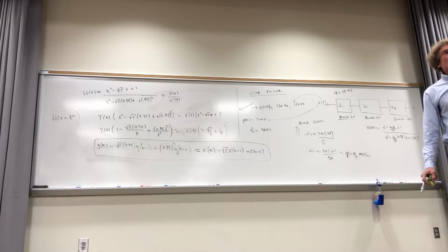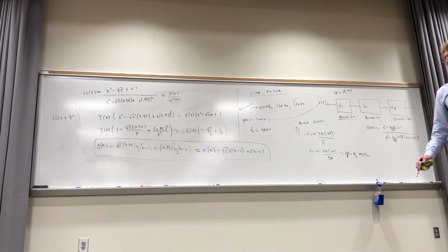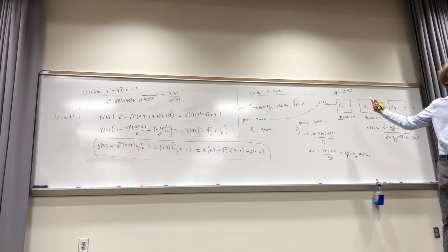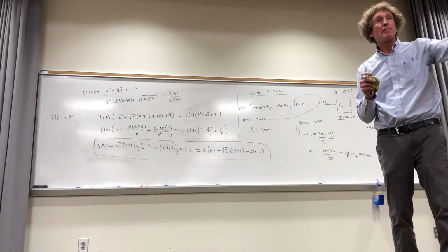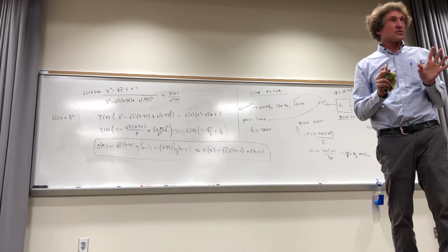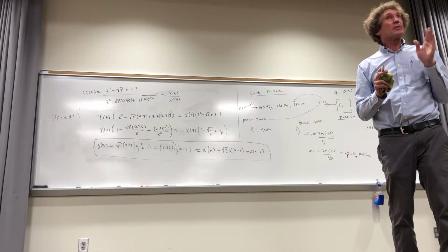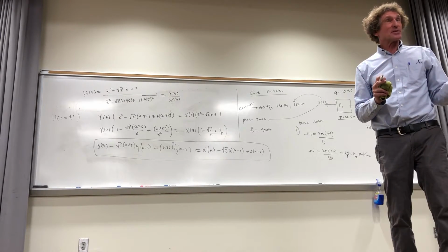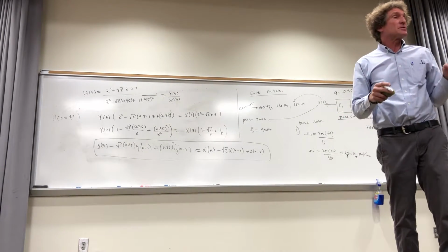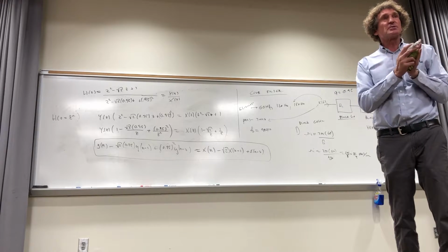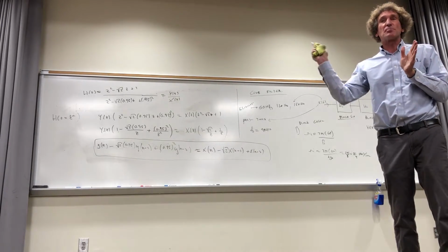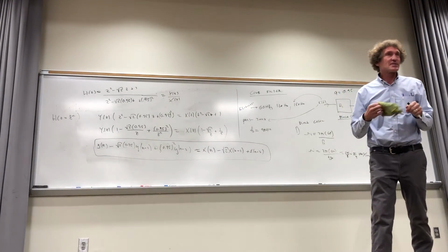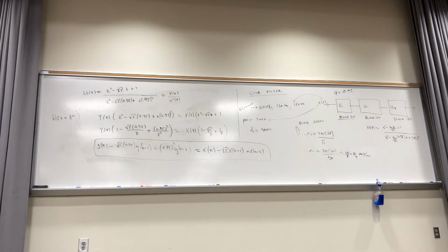Now, that doesn't seem like a lot, but what if all of a sudden you don't have 3 harmonics, suppose you have 33 harmonics. Where I'm going with this is when you have square waves, a lot of times you don't have 1 harmonic to worry about, you have a whole lot. And that's why comb filters are necessary, because they work at the harmonic, but there is an easier way. This is perfectly acceptable if only those 3 frequencies are what you're worried about. But many times it isn't just 3, it's a lot more. And they're periodic, so you want something that would eliminate all these problem children. That's where we're going next. But this doesn't always work. There are certain conditions where I'm about to show you.